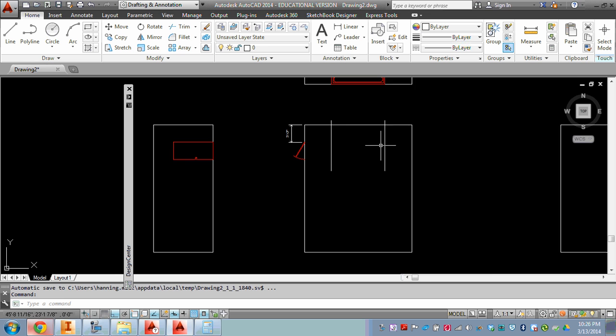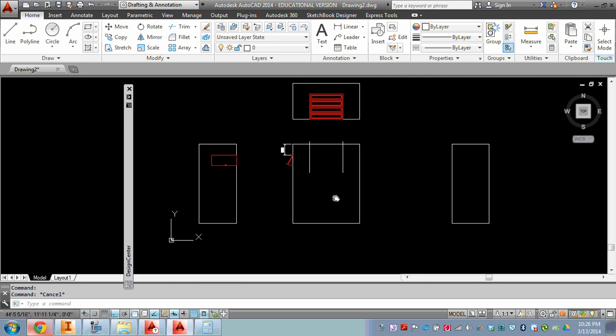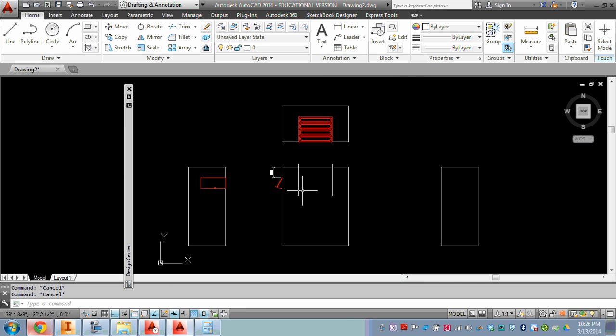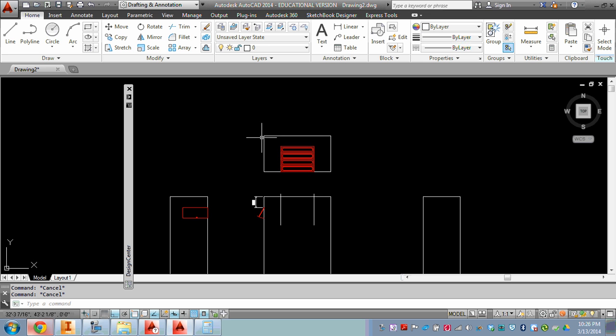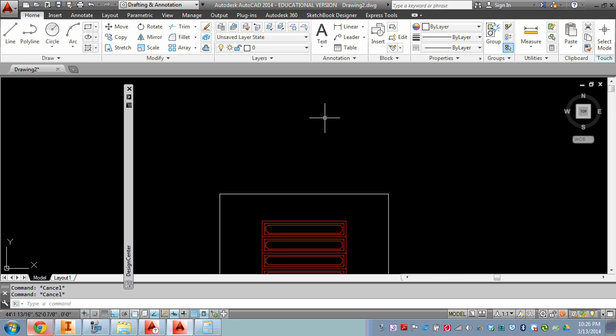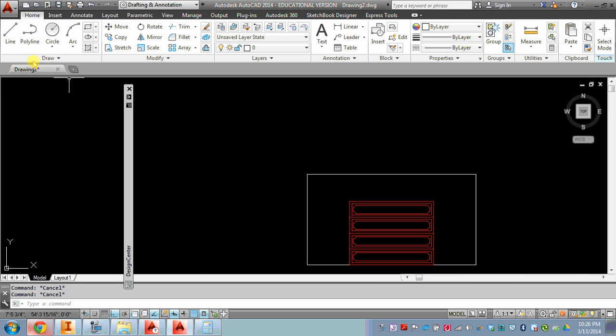Okay, so now that represents our garage, really. Next thing we have to figure out is we have a 5/12 pitch. A 5/12 pitch of a roof doesn't have a length, but it's determined by the horizontal and vertical measurements. So we don't know how tall the peak is. In order to do that, we're going to define an angle to this. If we draw a line, 5/12 means up 5 inches, it could even be 5 feet, up 5 over 12. So that's how you get that.